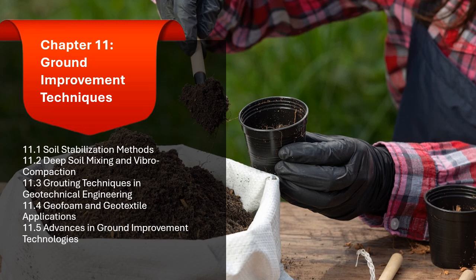Cost variability. While generally cost-effective, the cost of grouting can vary depending on the depth of injection, type of grout used, and site conditions. It may not always be the most economical option for all types of projects. Time-consuming. Some grouting techniques, particularly chemical grouting or jet grouting, can be time-consuming and require careful monitoring to ensure the desired results are achieved.